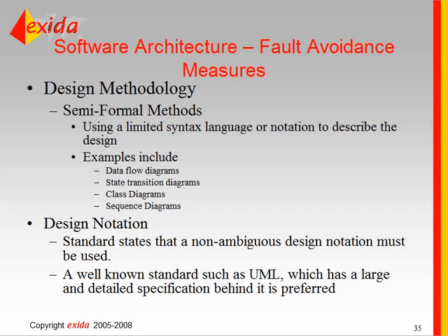All right, so the design methodology. For SIL 3, it's required that you use semi-formal methods similar to what we discussed for the requirements. It's essentially a more stringent way to define your design. Semi-formal methods are essentially defined as using a limited syntax language or notation to describe the design.